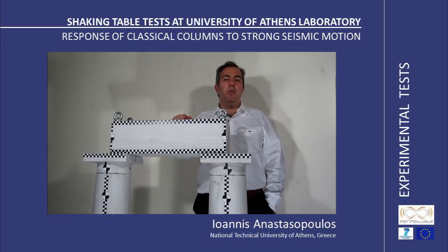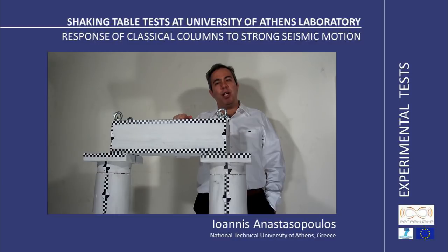In each case, we measured displacements, rotations and accelerations of each drum, and it was proven that exactly because the drums are not connected to each other, they can rotate and slide, and this leads to tremendous dissipation of energy. Actually, based on the results of the shaking table tests, it may be concluded that such monuments can easily last for 20 more centuries.